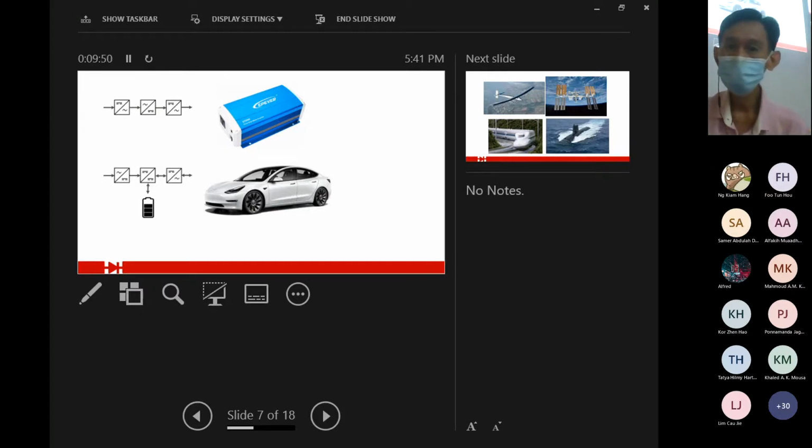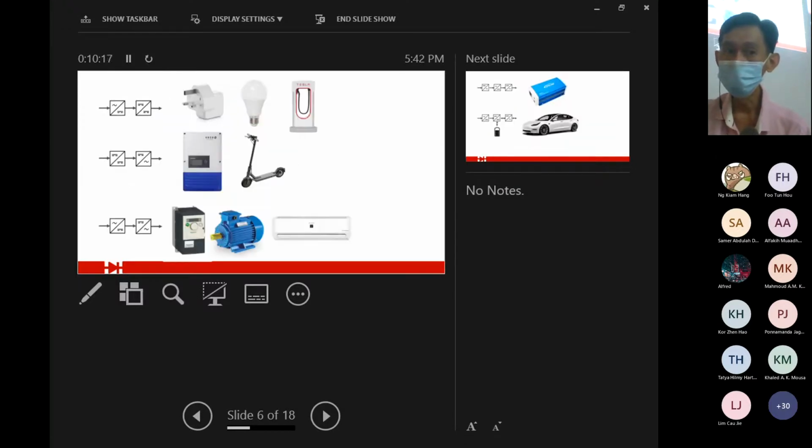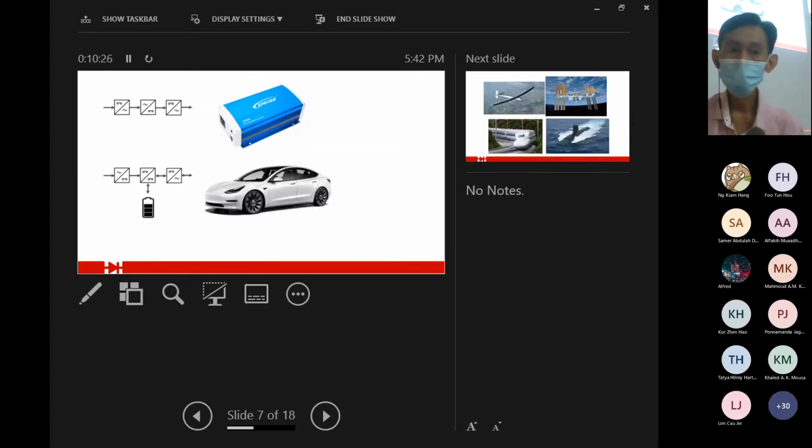Like this car battery inverter, it is DC to AC, AC to DC again, and DC to AC. Of course, there is a reason for every step. And for EV, when you charge it is AC to DC, DC to DC, and then this is bi-directional. Now, all the while I've been showing you is one direction only, from the source to the load. Unidirectional. A converter can be bi-directional, meaning that it can go in both directions. And this is what we call a bi-directional converter.